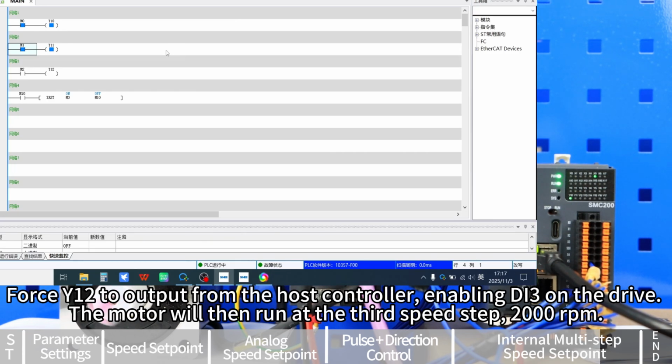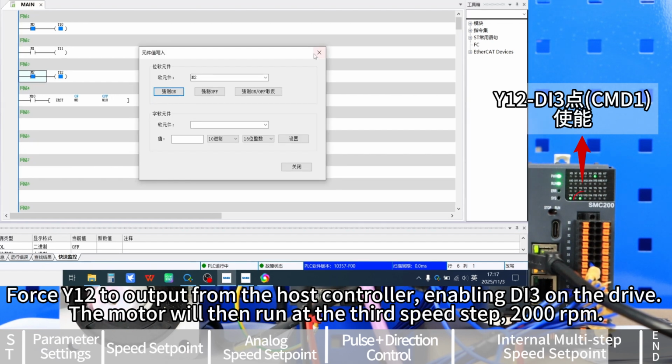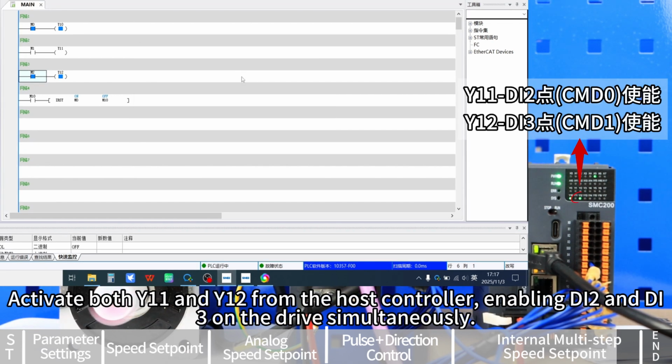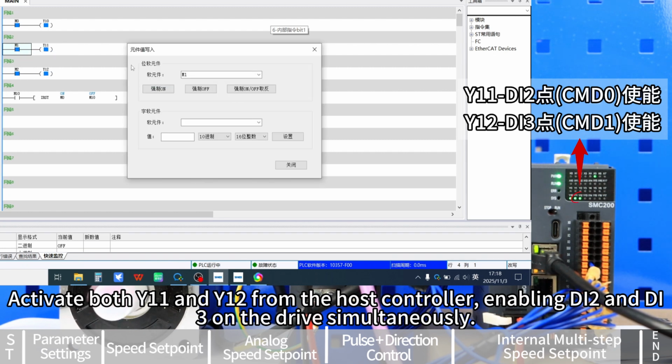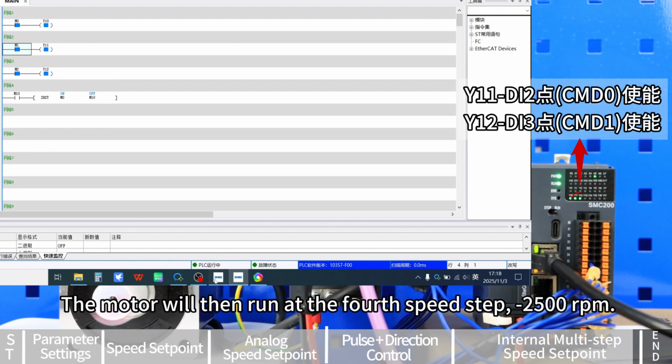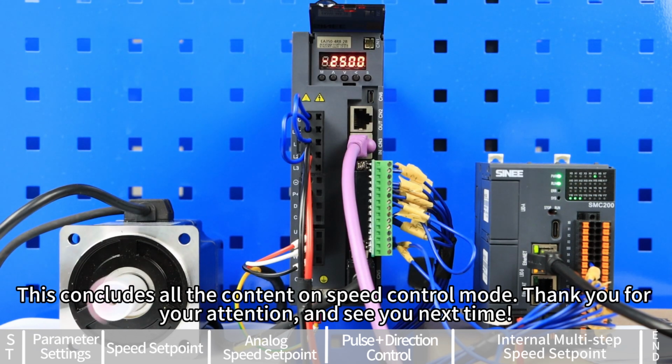Force Y12 to output from the host controller, enabling DI3 on the drive. The motor will then run at the third speed step, 2000 revolutions per minute. Activate both Y11 and Y12 from the host controller, enabling DI2 and DI3 on the drive simultaneously. The motor will then run at the fourth speed step, minus 2500 revolutions per minute. This concludes all the content on speed control mode.